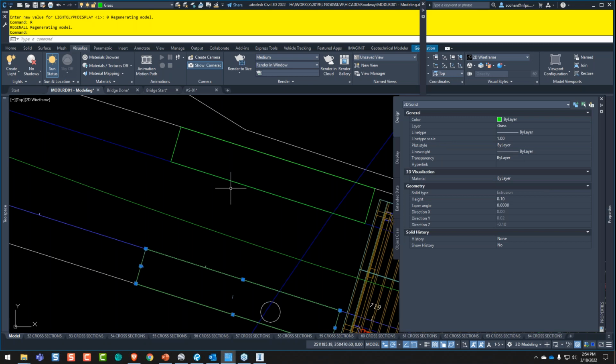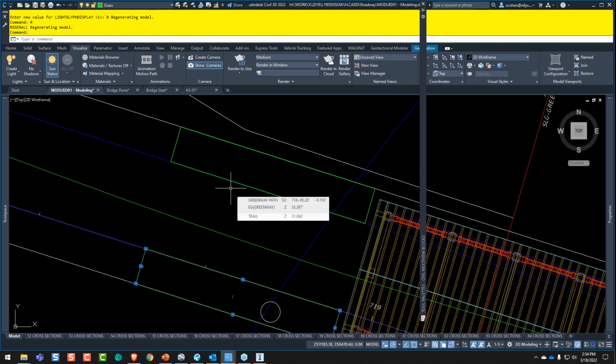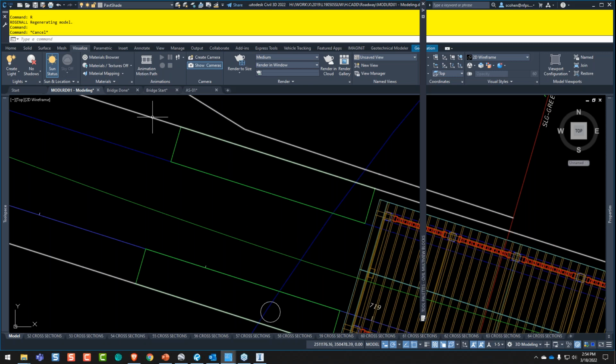It started out as a region, I'm sorry, a 3D polyline, and then I just extruded it because I snapped to where the shape was. See how the chord is right here? So I just snapped in 3D. It's basically going from the edge of the path to the daylight line or the slope line that I drew in there. Then what I did was I exported that, because I don't want to do the whole file, right?